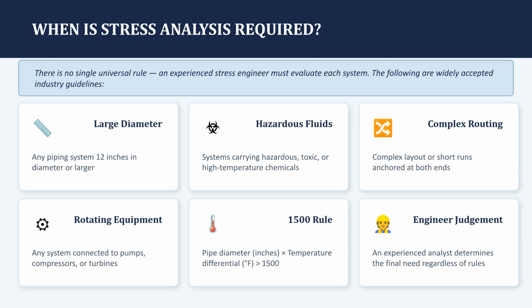That combination often creates high stress concentrations, so it needs to be checked. 4. Rotating equipment. Any pipe connected to pumps, compressors, or turbines needs analysis, because as we covered on the previous slides, this connected equipment has very sensitive nozzle load limits.